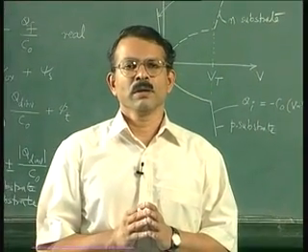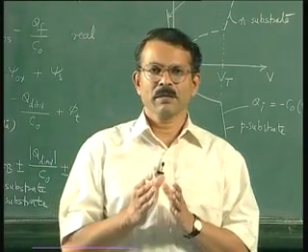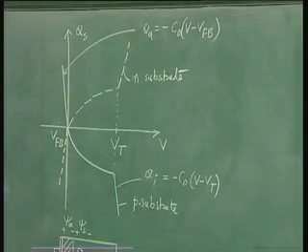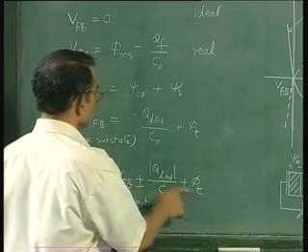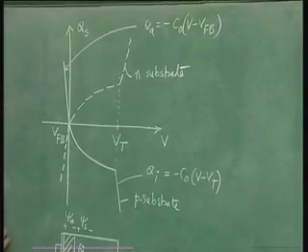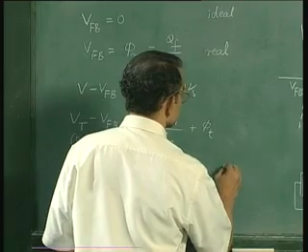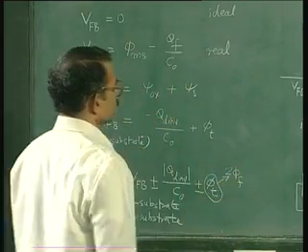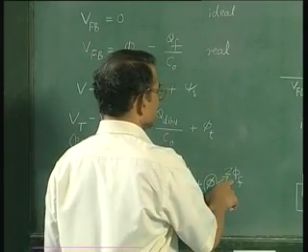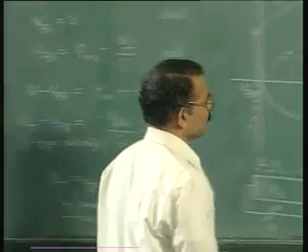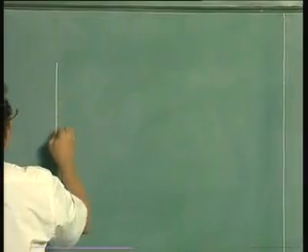Now before we take up the capacitance voltage characteristics based on this charge versus voltage characteristics, let us explain why this term phi t here in the threshold voltage is also referred to as twice phi f. So what is this twice phi f? To understand this, we should look at the energy band diagram. So look at the energy band diagram at inversion.